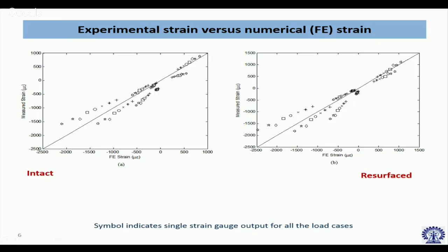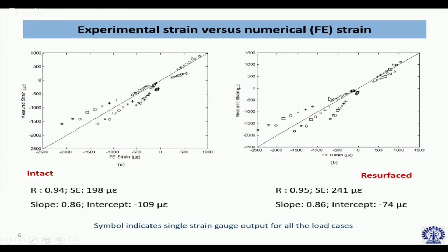But in reality, we do not always get that. So there are some deviations in the results which also need to be analyzed. So we perform a statistical analysis, the standard statistical linear regression testing of hypothesis, to see how well the FE predictions actually predict the actual measurement.